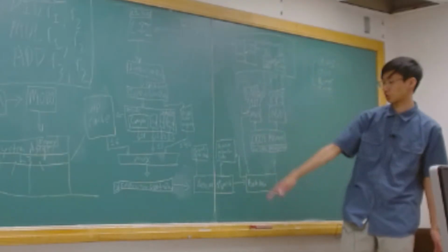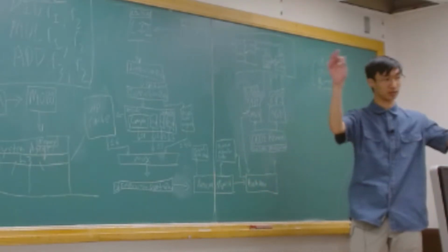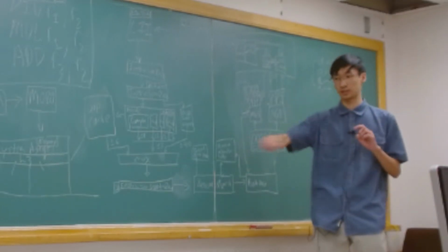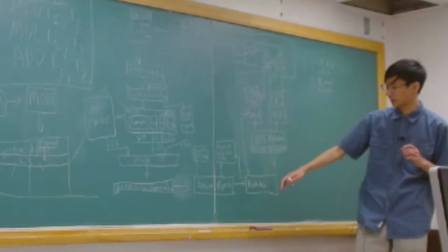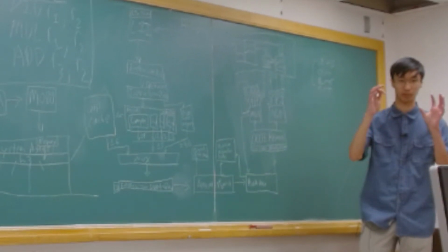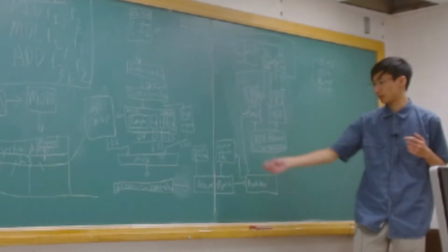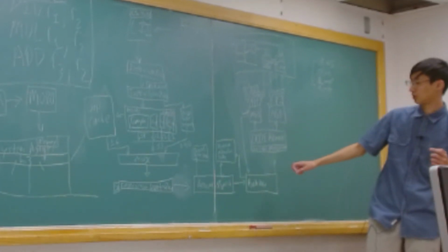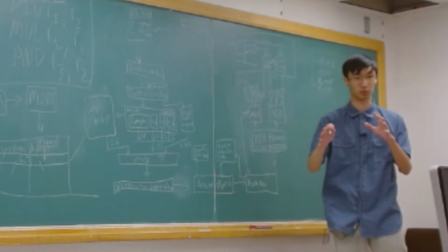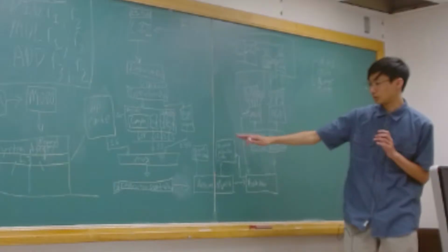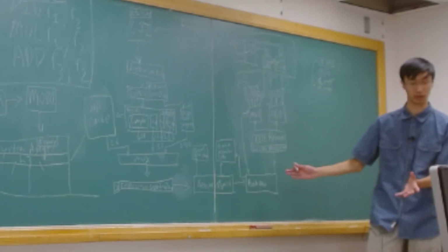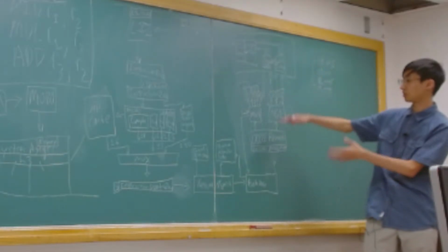This is where out of order starts appearing, and you will start using that algorithm, the scoreboard or the Tomasulo algorithm. Scoreboarding is the older one, Tomasulo is the newer one, and Tomasulo is a little better in terms of memory usage and the amount of stuff you have to track. And so we'll use that to rename our registers, like I talked about earlier, where we'll just create new registers every time we modify data, and then we will add them to the register allocation table. We'll update the reorder buffer with the entries, and then this operation will go through.